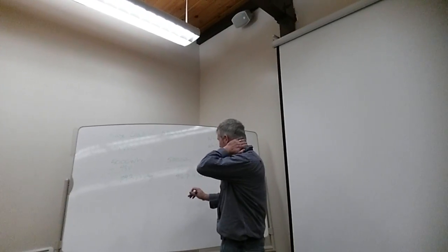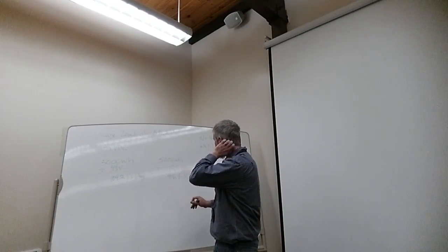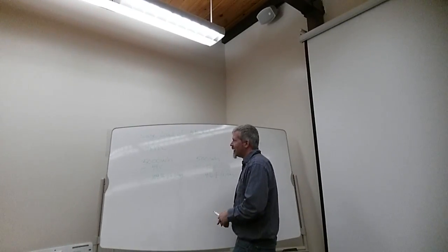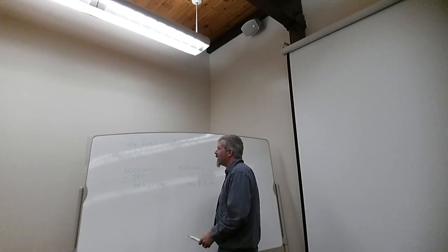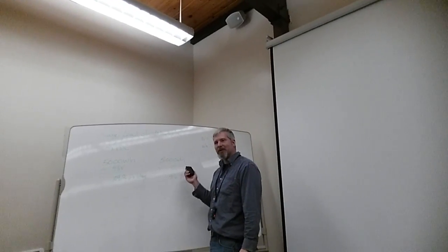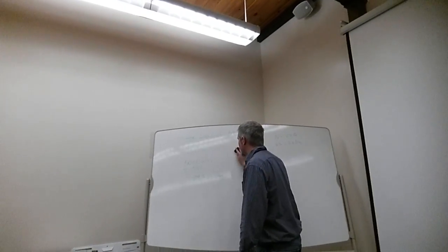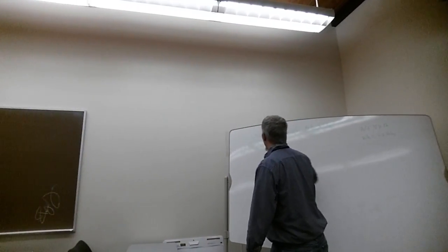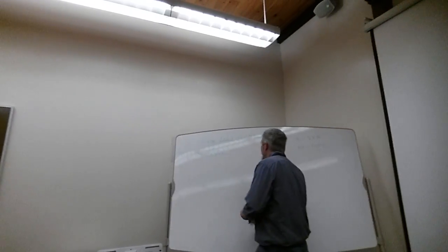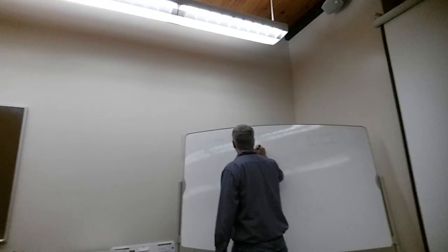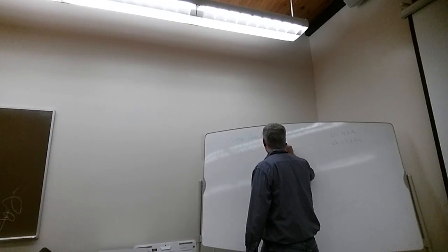So in this example here, trying to figure out where we want to go. Do you mind, can I erase some of this? Do you guys care? Because I want to kind of normalize this a little bit, because it's way out of control. So let's say we do want to get to this 48 volts. We have 5 kilowatt hours a day. We know that there are 4 peak sun hours.